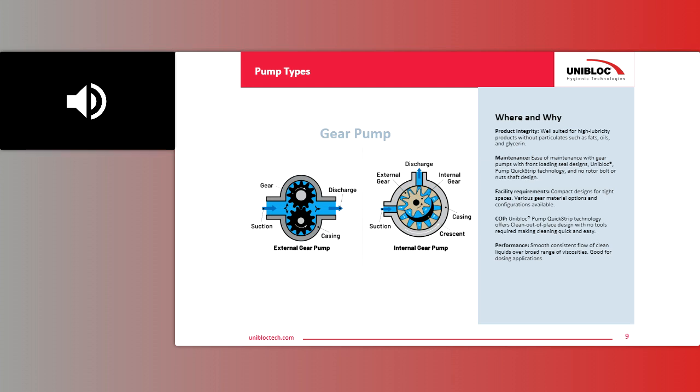They're typically designed for what we call thin, clean liquids. Think of oils, fats, glycerin, things like that. They also self-lubricate. So that's typically what they're for. Most of these pumps are on the medium to small size, so from a 1/2-inch up to maybe a 2-inch typically. So you don't have a wide range like on the previous slide on the rotary lobe pumps. They are a lower cost pump technology. There's only one driving shaft in this technology.